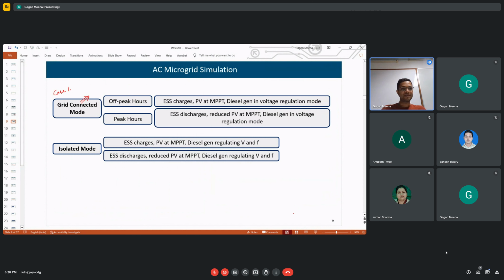The current in this faulted phase is increased, but the currents in the other two phases are not the same, meaning they are at normal values. That is why there is unbalance. Because in a fault there is unbalance, but that will not always happen. Suppose there is a triple LG fault, then there is no unbalance. So it will depend upon the type of fault, and most faults lead to unbalance.